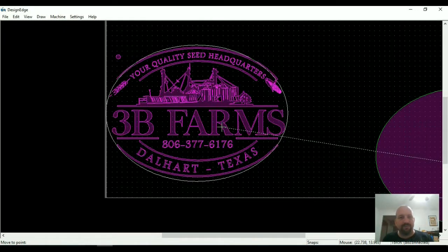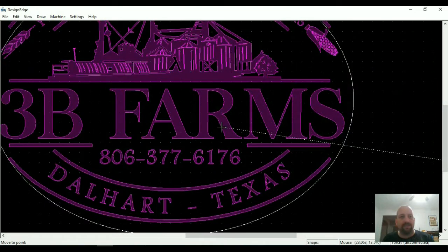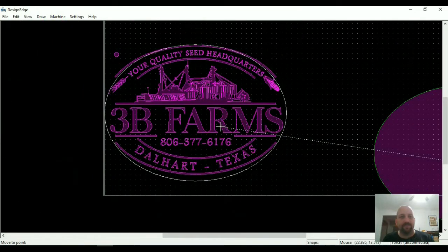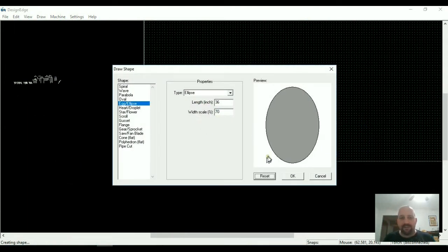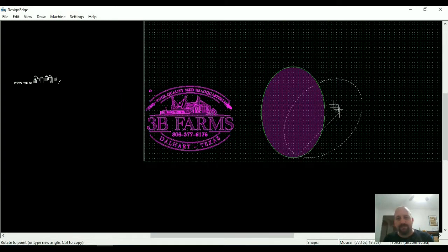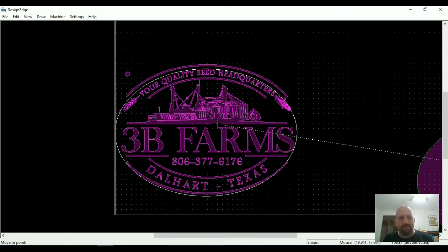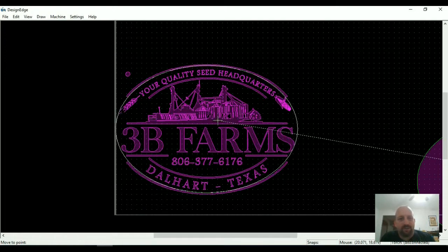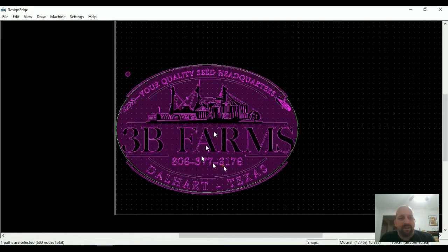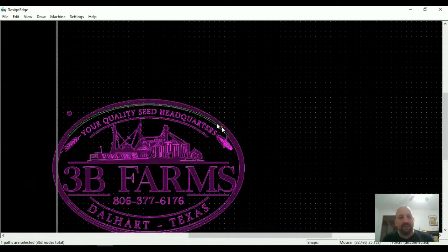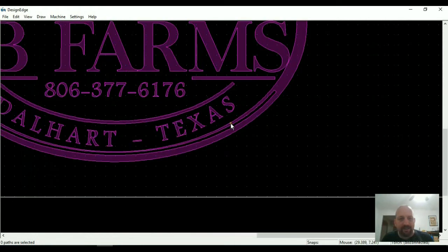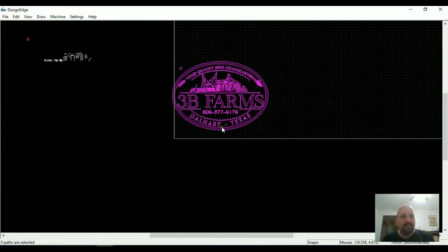That's pretty close. Maybe even a little skinnier still. I want to get it fairly close, so the text doesn't look like it's at the wrong angle. There we go. 70% is going to work perfect. And so for this to work, I'm going to have to offset that out, and so we're going to be a little bigger. So that's a 1 inch outside offset. I'm going to delete that top and bottom text piece.